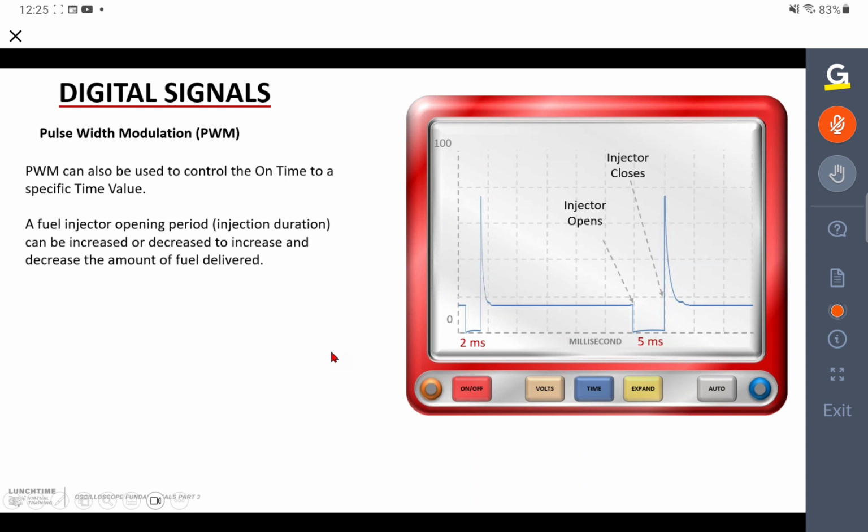And again, as with all of the examples we've been looking at so far, what you need to do, of course, is get some good samples. Now, some of the diagnostic equipment manufacturers, the oscilloscope manufacturers, have their own libraries, and they're handy. It's a good start point. But whenever you get the opportunity, just hook up to a good car. If you've got an oscilloscope that allows you to save the images, maybe even print them out. Do as many as you can, because you can't really tell a bad one until you've seen a good one.